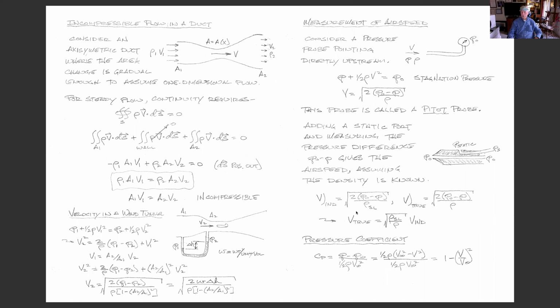And most commercial airplanes, even up to 35, 40,000 feet, fly at constant indicated airspeed. That's why you want to fly high, because in fact, you're going a lot faster. I used to hang people up in MAE 158 with that. I tell them, okay, you're going to fly at constant indicated airspeed. And you find out that at constant indicated airspeed, your drag is constant and that you're going a lot faster. That's why you try and fly high.